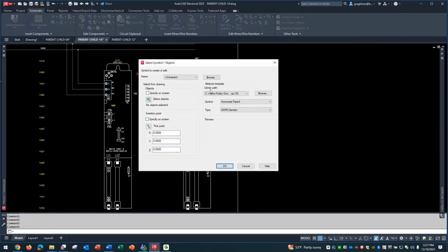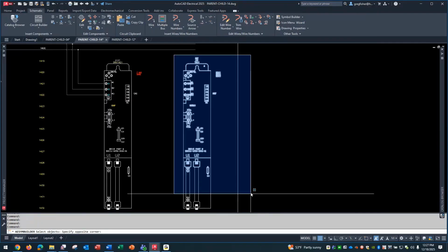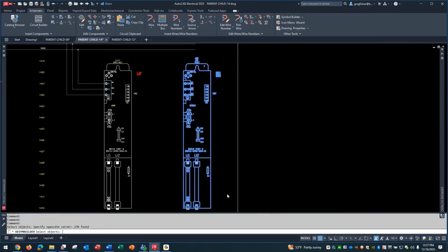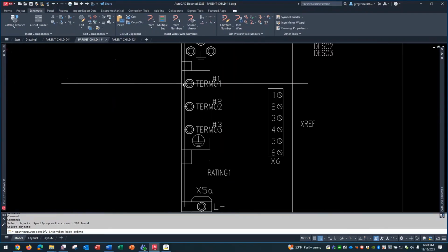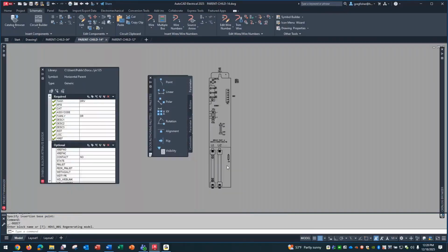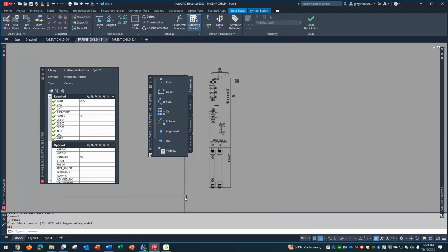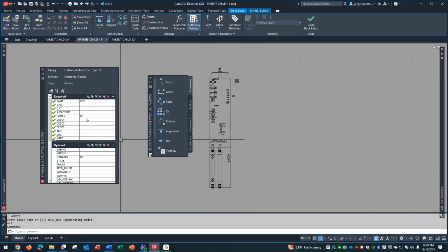So when you do create the symbol itself, once again, I'll go back to selecting objects, picking a base point. I'm going to leave it on generic. And the key here, now this is already filled in because it's already built into the symbol, but normally, when you go to generic, your family attribute is going to be blank.